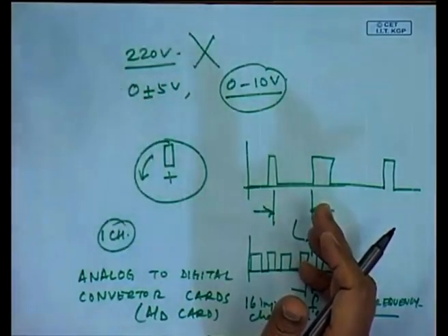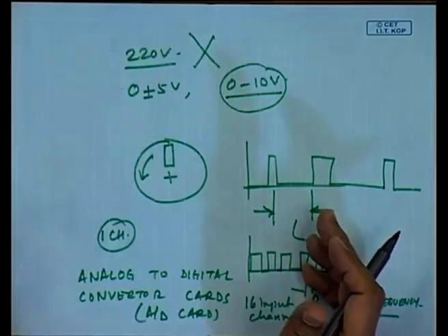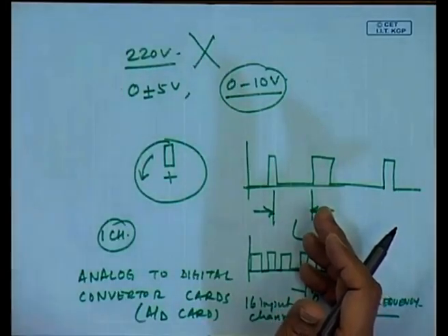And then from the external world, you can plug in wires which are carrying the analog signals into the A to D card, and then after the conversion the digital data will go into the computer bus, and then the computer memory devices will have access to that, and the control CPU will have access to such data.